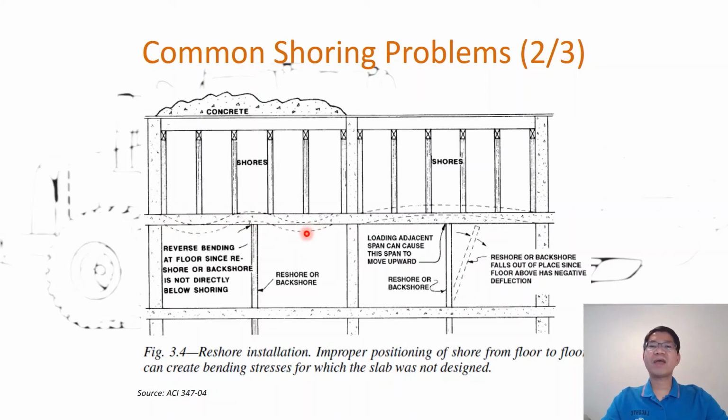And when it deflects the other way, that may not be the intended design from the structural designer. Because when you design concrete or any structure, we assume what the loads should be after construction, during the permanent structure when the structure is put in use. But this is during the construction. We make sure that it will not create a load that cannot be anticipated during the design.